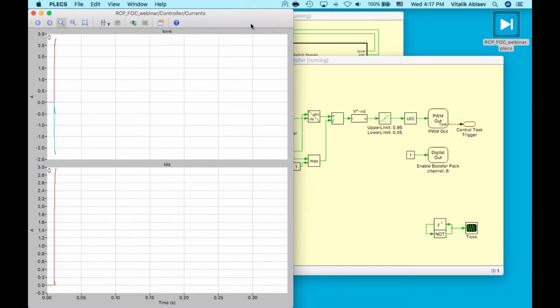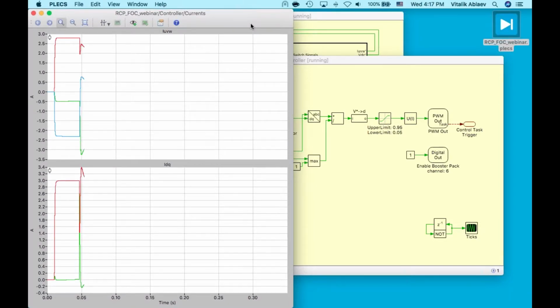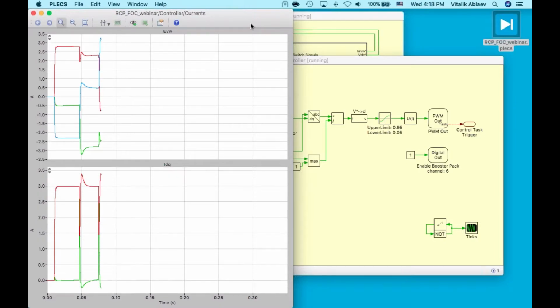Initially, as I mentioned, the motor will function off of the Hall sensor's input in order to determine the rotor position. So what we will see here is the 6-step commutation in our phase currents. When the rotor passes a sensor, it produces either a high or a low signal to indicate which rotor pole, north or south, has passed. The switching of the 3 Hall effect sensors from high to low or from low to high provides rotor position information every 60 degrees.